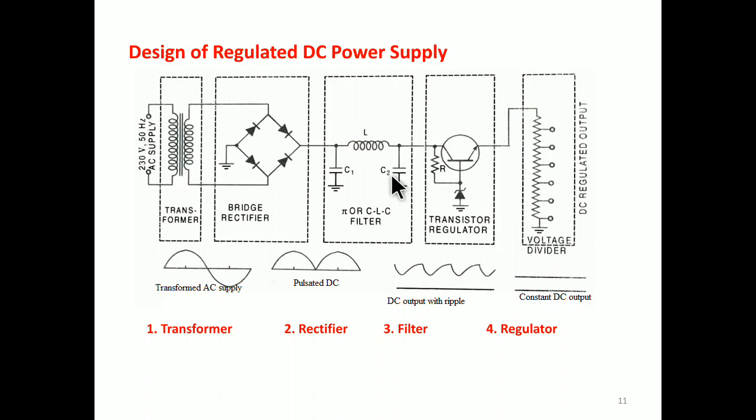Sometimes the DC voltage usually has some ripple or AC voltage variations. A regulating circuit uses this DC input to provide a DC voltage that not only has minimum ripple voltage, but also remains constant even if the input DC voltage varies somewhat or the load connected to the output changes.